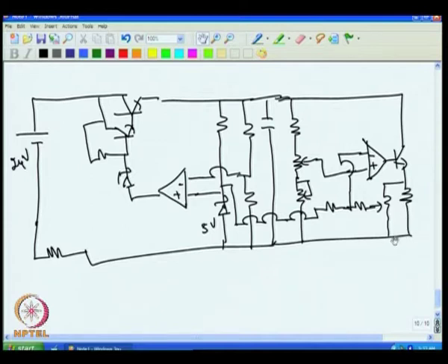This current of course is the same as this current, because the current flowing through this plus the current flowing through this, which is constant, then some current flowing here, that is also constant, some current flowing here, that is also constant. Since all the other currents are constant and this is the only variable, once you vary this, the current changes. So, one can adjust the 4 and 20 milliampere by adjusting this 0 part. For example, this is the 0 part, this is the span part.